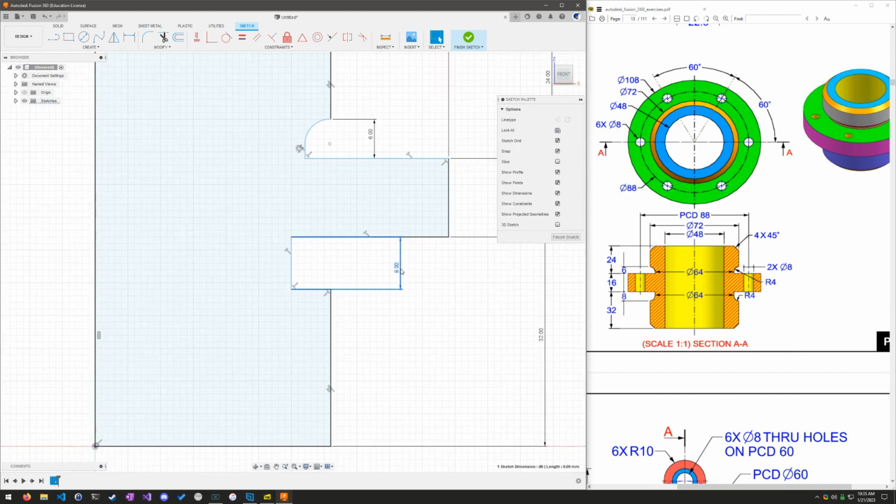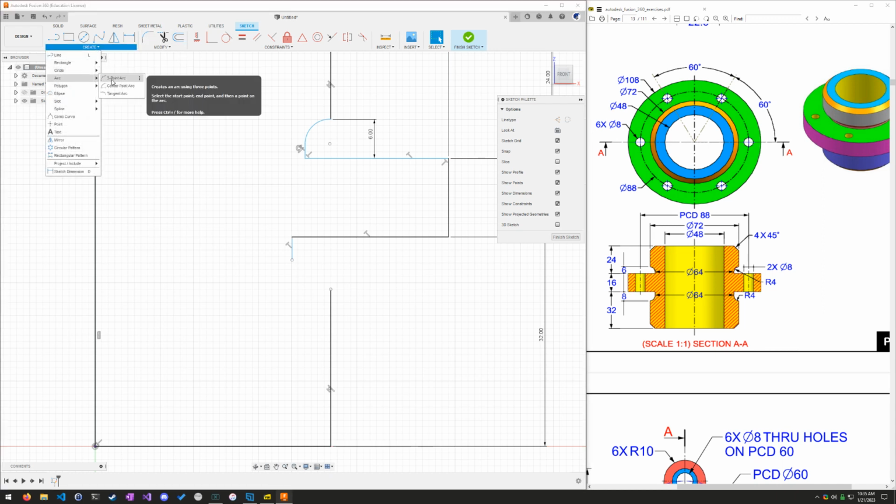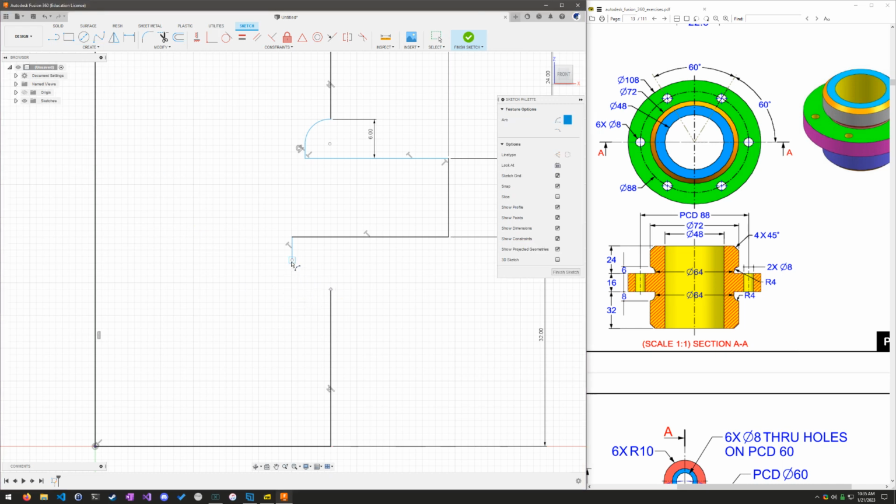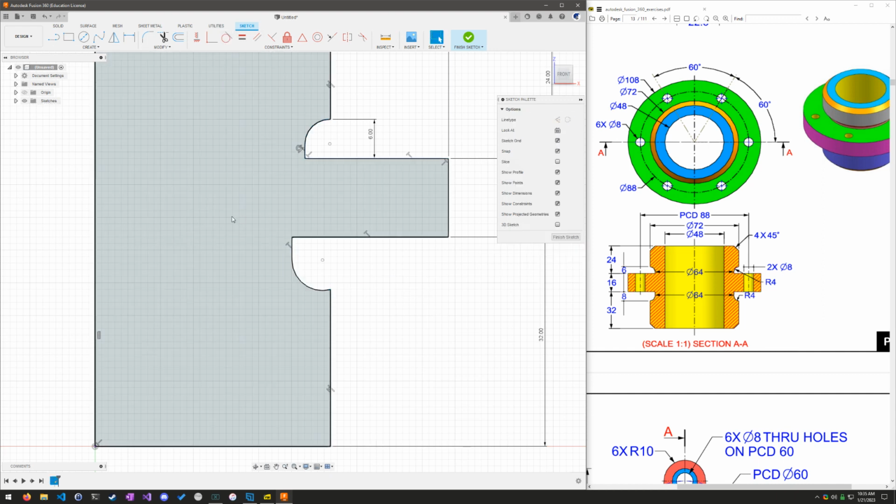Again, we'll delete this 8, and we'll delete this horizontal line right here. I'm going to drag this dot up so I can create a 3-point arc, create arc, 3-point arc, and go dot to dot and bring in my arc. That already snapped tangent there for me because I held my mouse in a way that was tangent to that line. If that doesn't do that automatically for you, don't forget to use the tangent tool. Actually, you know what? I'll just delete that so I can do it. Tangent, arc to line is what you should do. Okay.